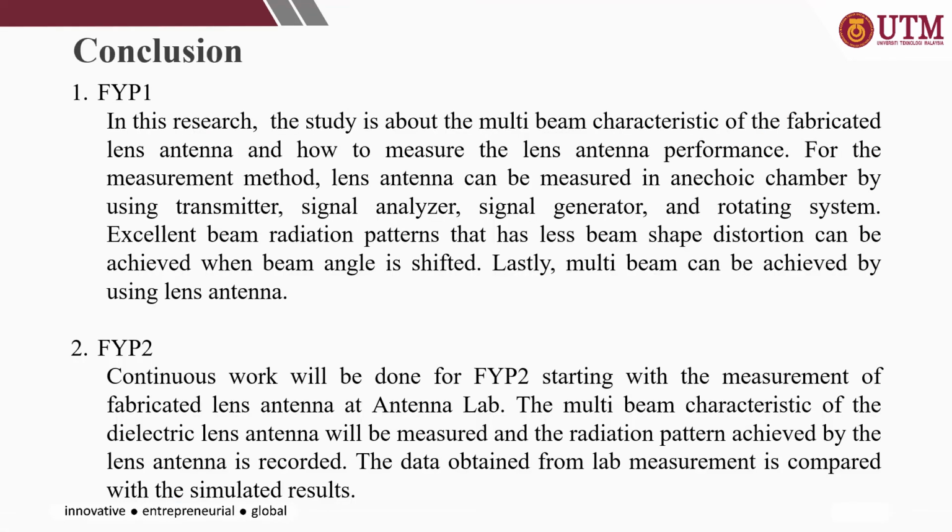So, this is the conclusion for my FYP. For FYP1, it is about the study of fabricated lens antenna and how to measure the lens antenna performance. Lens antenna can be measured in an anechoic chamber by using a transmitter, signal analyzer, signal generator, and rotating system. Multi-beam can be achieved by using lens antenna.